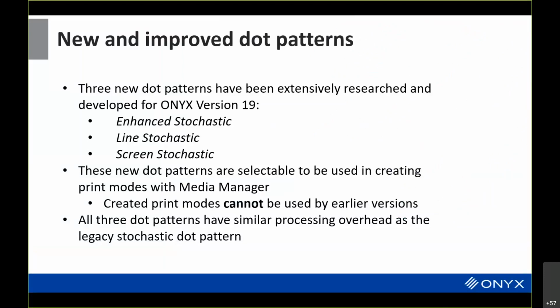There were some people complaining about the dot patterns. Some of the aspects of the dot patterns were that they kind of got clumpy, they weren't smooth, potentially resulting in banding on printers. And so we spent some time developing 3 new dot patterns that are now part of the version 19 software. And they are enhanced stochastic, line stochastic, and screen stochastic.